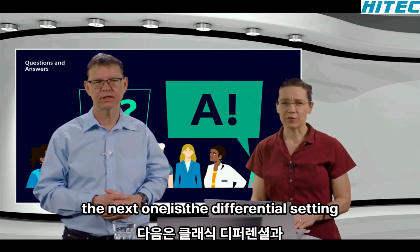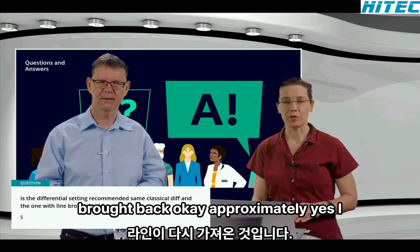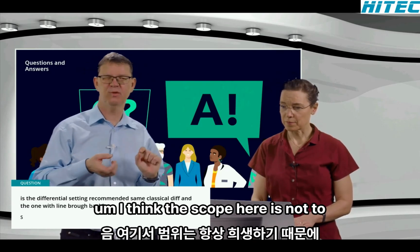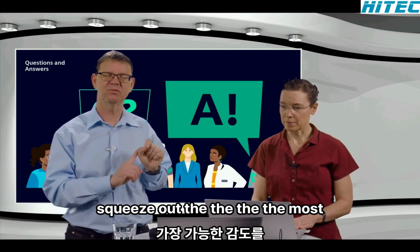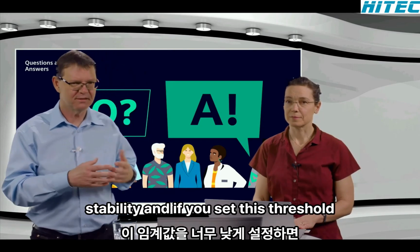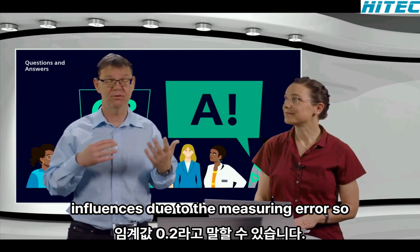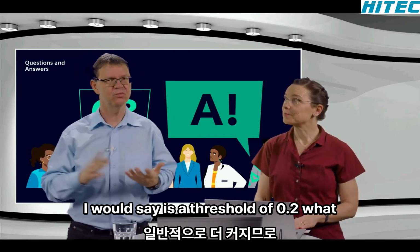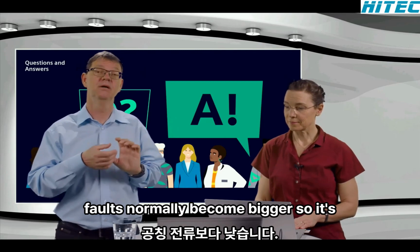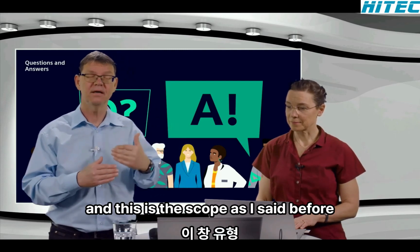Is the differential setting recommended the same as for classical differential and the one with the line brought back? Approximately, yes. The scope here is not to squeeze out the most possible sensitivity, because you always sacrifice a little bit of stability. If you set this threshold too low, you might get influences due to the measuring error. So I would say a threshold of 0.2, which we have as a standard threshold, is good, because the faults you detect normally become bigger. It's not the point to detect 0.001. 0.2 is below the nominal current, and this is the scope.